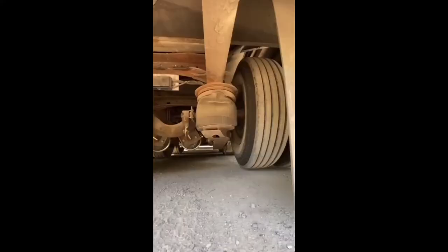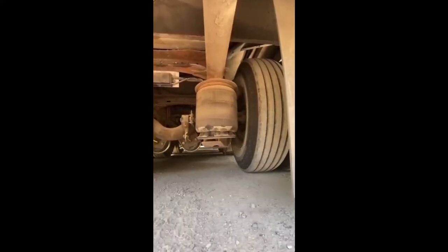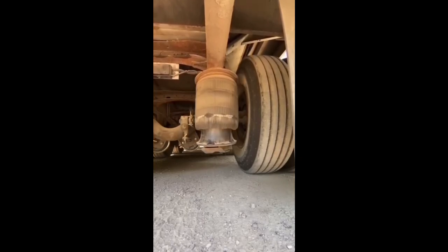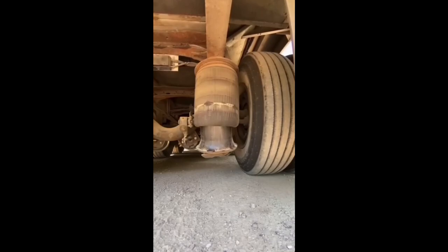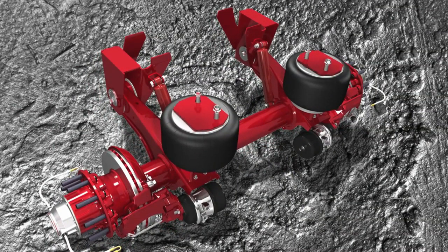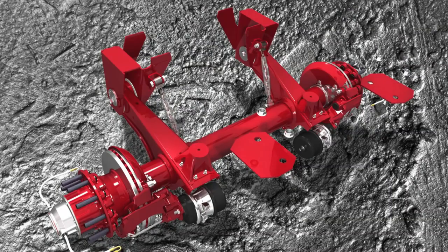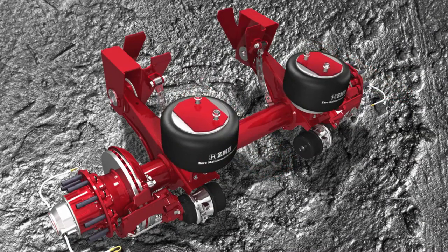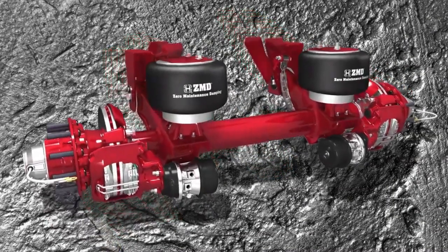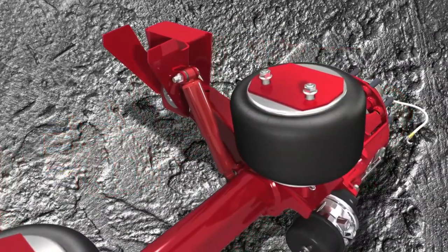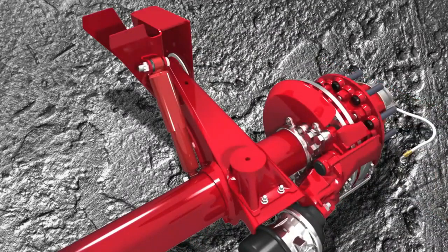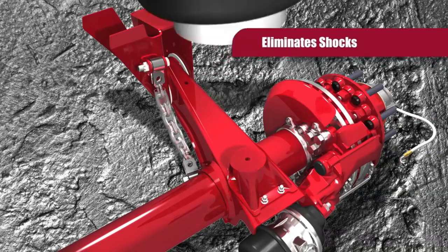Fourth is the airbag. Airbags are essentially simple rubber components designed to contain and hold compressed air. They are often referred to as air bellows. There are different types of airbags, including piston-type and elongated bellow-type variants. These airbags leverage the compressive properties of both air and rubber to absorb vibrations and facilitate the adjustment of the vehicle's height, either raising or lowering it as needed. To achieve this, compressed air is introduced into the airbags, inflating them and subsequently altering the suspension height. Typically, these airbags are positioned between the vehicle's frame and its axles.